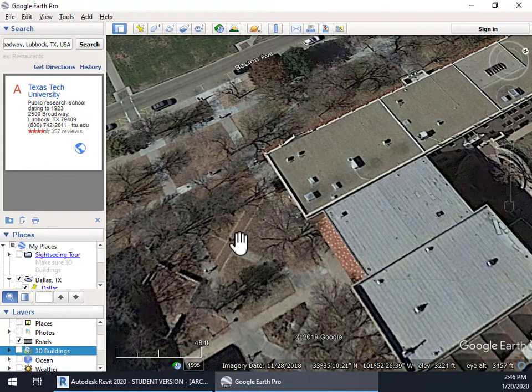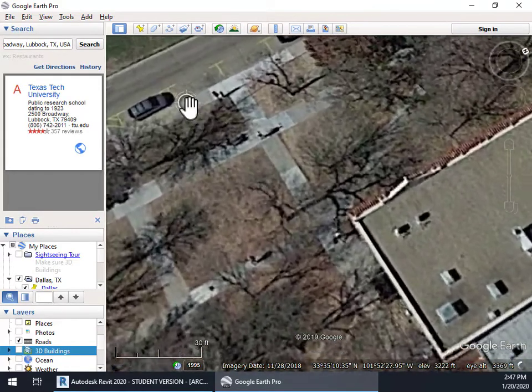Now, I have to remember, Google Maps is not really accurate. We could be a foot or 2 feet off on the elevations here. So there's probably more gradation, and it's only going to give us increments of a foot. So this might be 3224.5 and this might be 3225, or something. But nonetheless, it'll give us some general idea. And so I'm going to assume that for the most part, this is pretty flat until we get to the street.